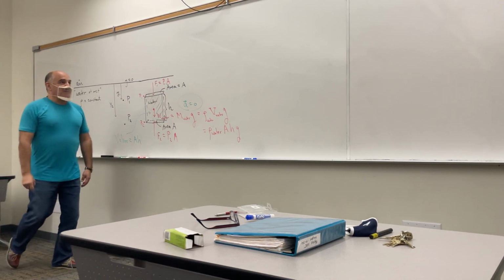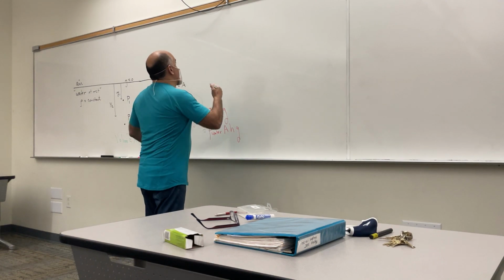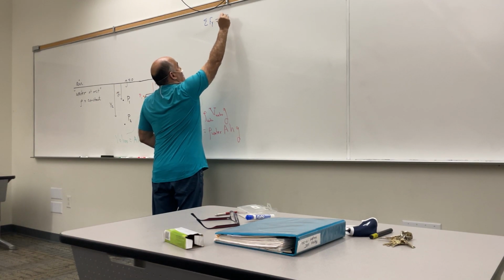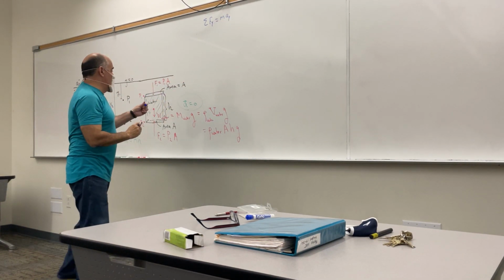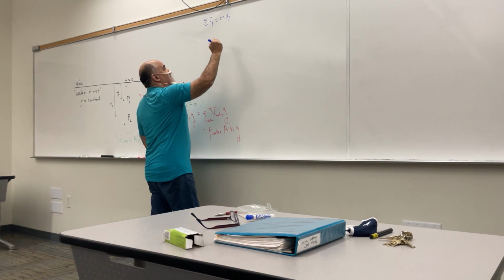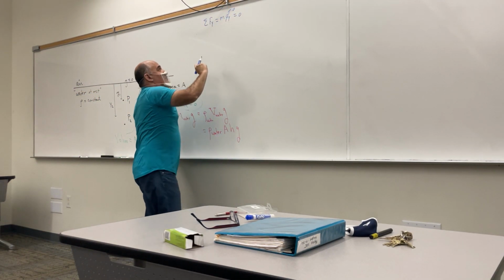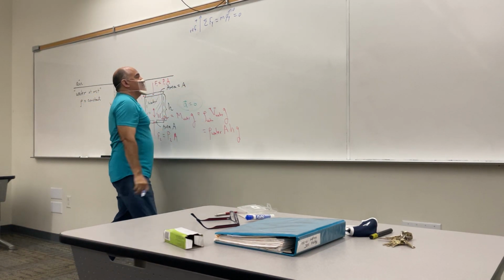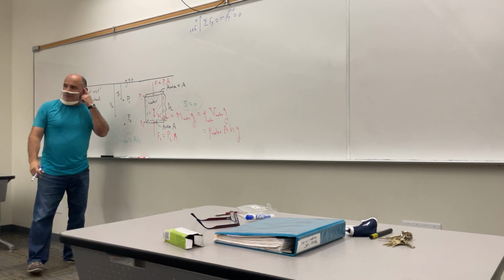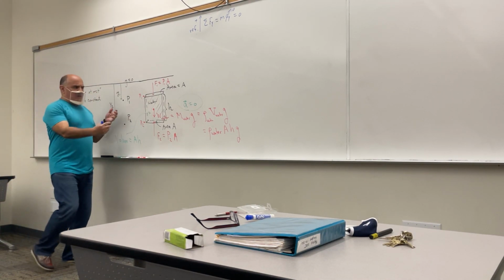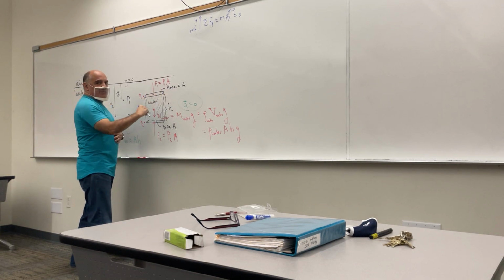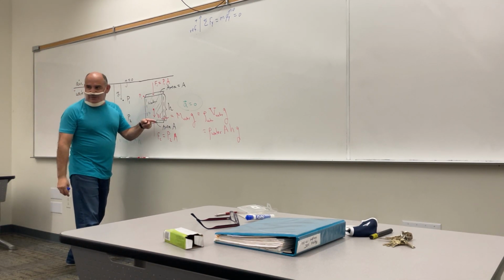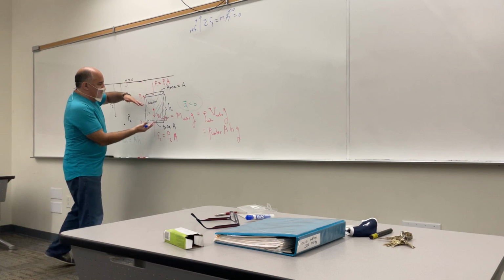And since this water that I'm considering a free body diagram of is at rest and stays at rest, the sum of the forces acting on that water has to be zero. So the sum of the y components of the forces acting on that water equals the mass multiplied by the y component of its acceleration, which is zero. Suppose I choose up as positive. I have three forces with a vertical component. There's water on the right pushing to the left, and water on the left pushing to the right, but those are horizontal, so I'm only considering the vertical components.